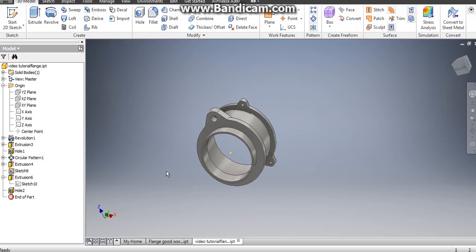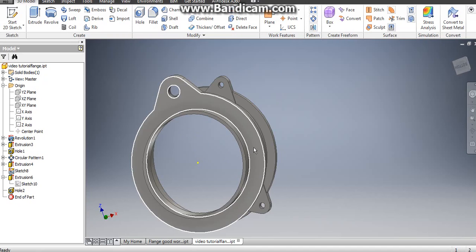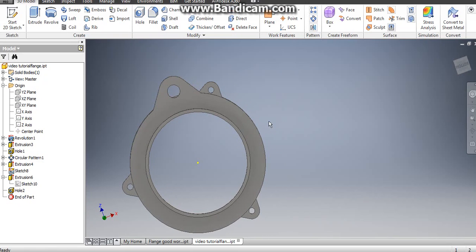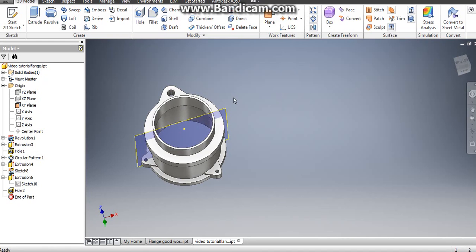We want that second style of wing and hole to be mirrored. We want it to be on the direct opposite side of our part as well. So the question becomes, what plane do we mirror it across? If we select our origin folder and hover over the different planes, you can see them show up. We are going to want to select the XY plane. Turn on the visibility of the XY plane. Now you can see it.